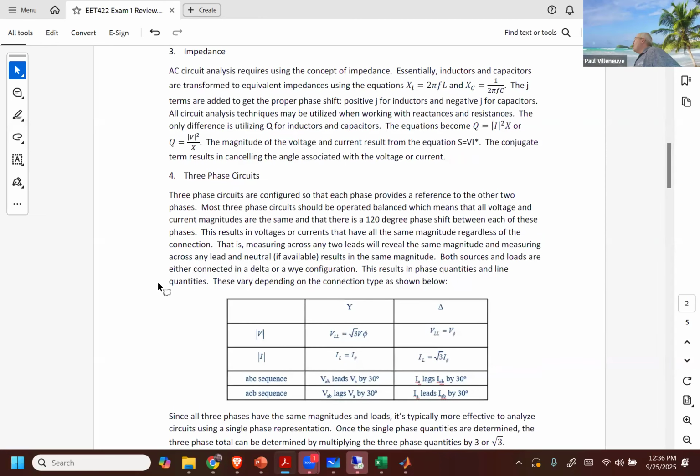So our term Z, to expand on that a little more, we do everything in terms of impedance. And impedance is the actual circuit limiting, if you will, parts that will limit the current. And impedance has real parts and reactive parts, or real parts plus the J term times the reactive parts. And how do you get XL and XC? That was just taking the derivative. If you remember, L dI/dt or C dV/dt introduces the 2 pi f either in the numerator or in the denominator. That's just because we have to take the derivatives or integral if necessary.